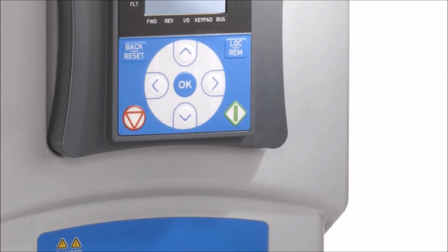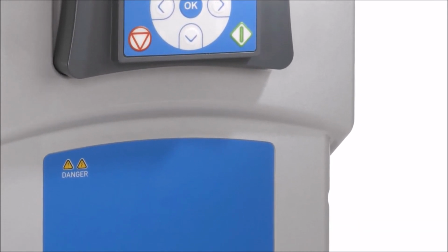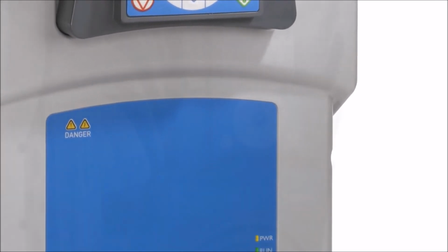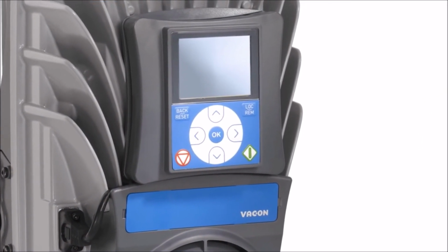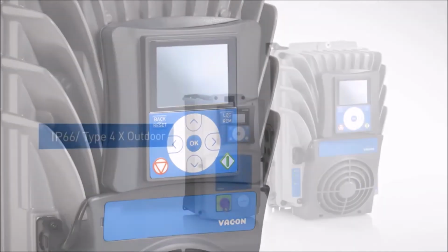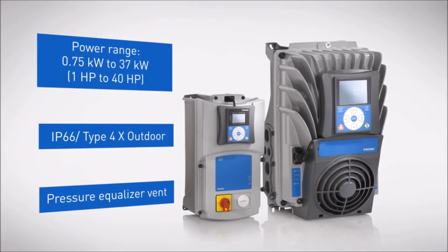VACON 20X is the most compact IP66/UL Type 4X drive on the market, while VACON 100X offers more power than any other drive with the same protection, up to 37 kilowatts. They both have a pressure equalizer vent around the enclosure, which acts as a barrier against condensation, dust, and dirt.